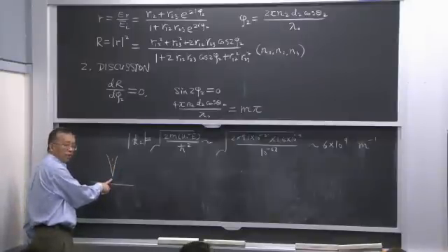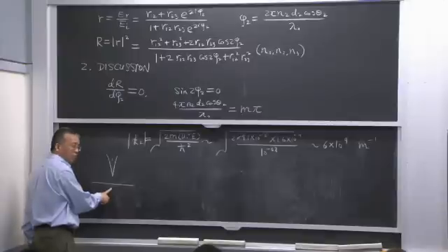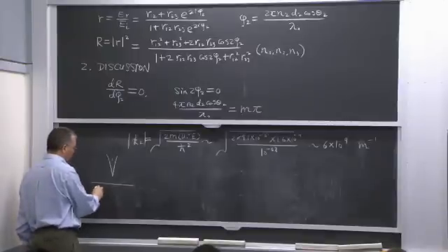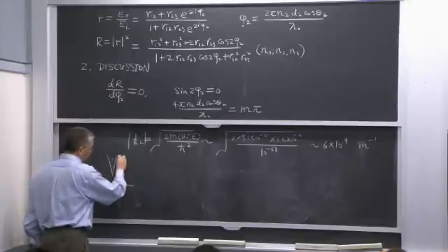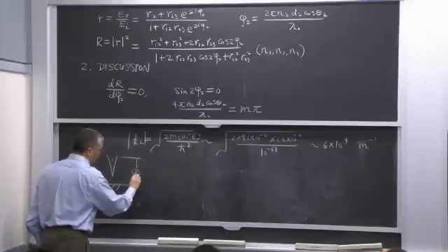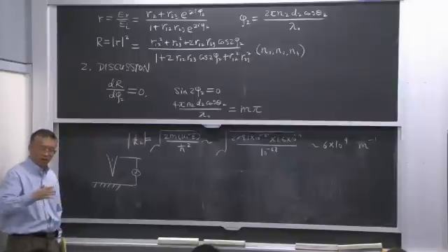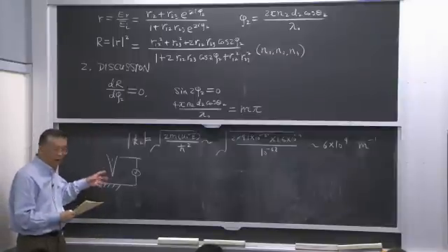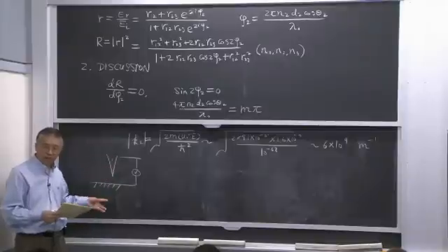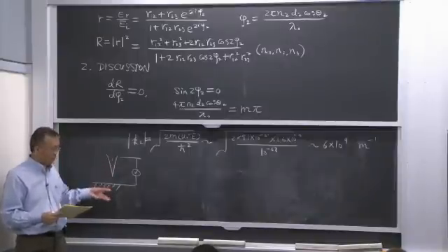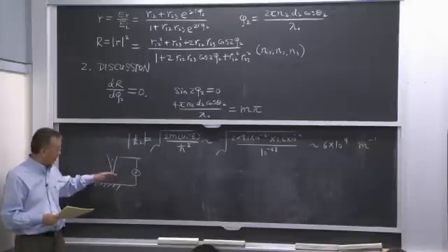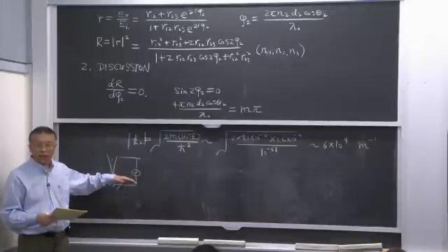Layer 2 is a vacuum. Layer 3 is the surface you're going to measure. You apply a bias voltage, and you scan over the surface. You measure current. You use your current as the feedback. That's tunneling. So based on the current as your feedback, you can maintain your height and not crash your tip.